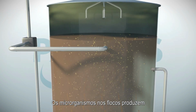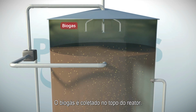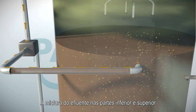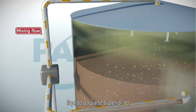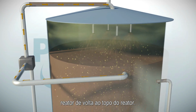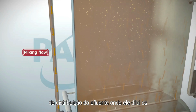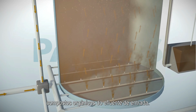The microorganisms in the flocks produce biogas throughout the whole reactor. The biogas is collected in the headspace of the reactor. The mixing in the bottom and top parts of the liquid in the reactor is the highest. This is due to the recirculation of liquid from the upper part of the reactor back to the top of the reactor. Another part of the liquid is recirculated back to the influent distribution system, where it dilutes the wastewater organic compounds.